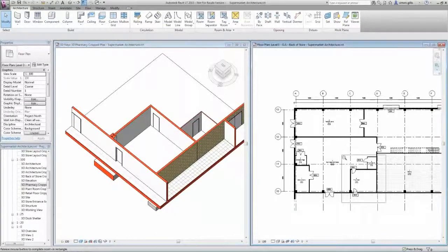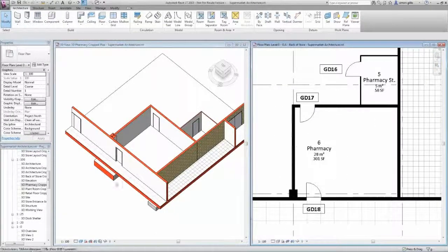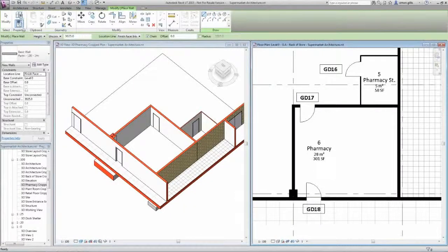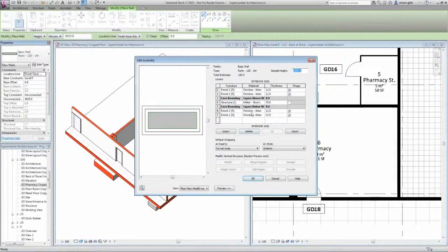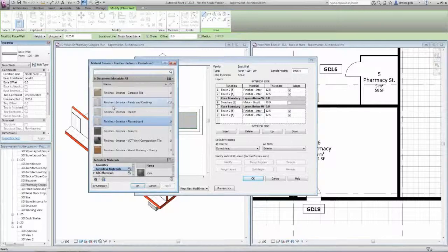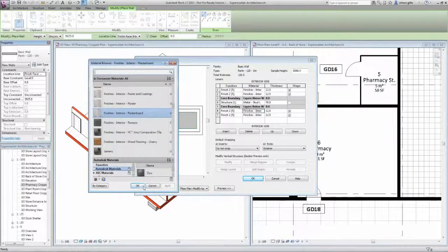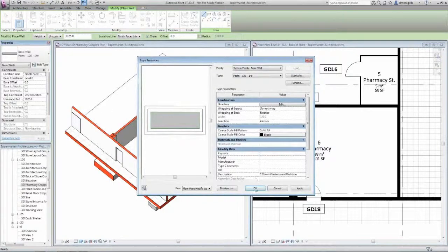Okay, what you're using with Revit is architectural components. You're designing with intelligent architectural objects. So unlike using lines, arcs, and circles, you're able here, for example, to specify a wall type. You can specify how that wall is made up, the different layers within that wall, and you can apply materials to it. And this isn't just for visualization purposes. This could also equally be for material takeoff.